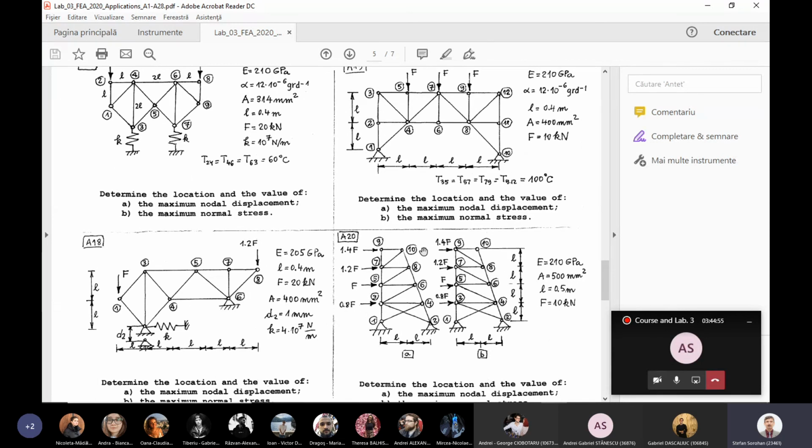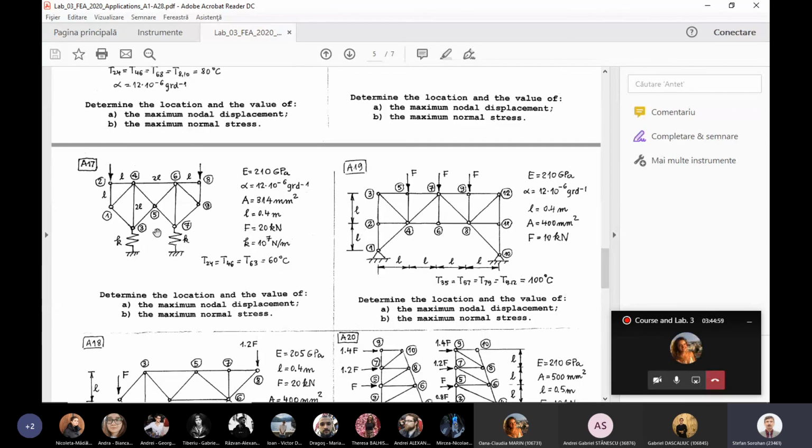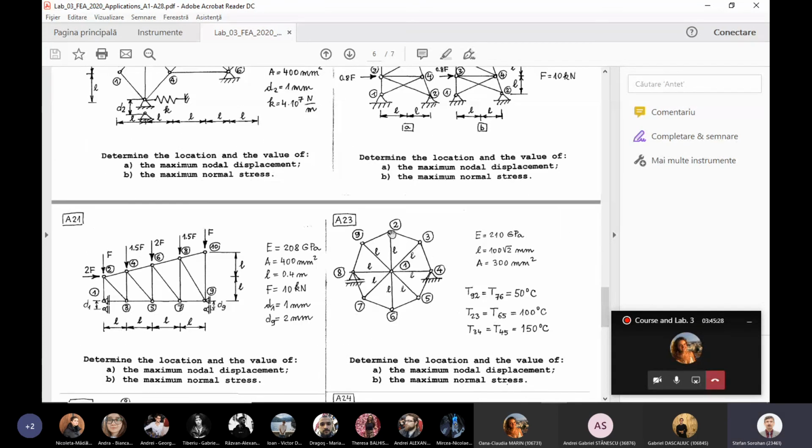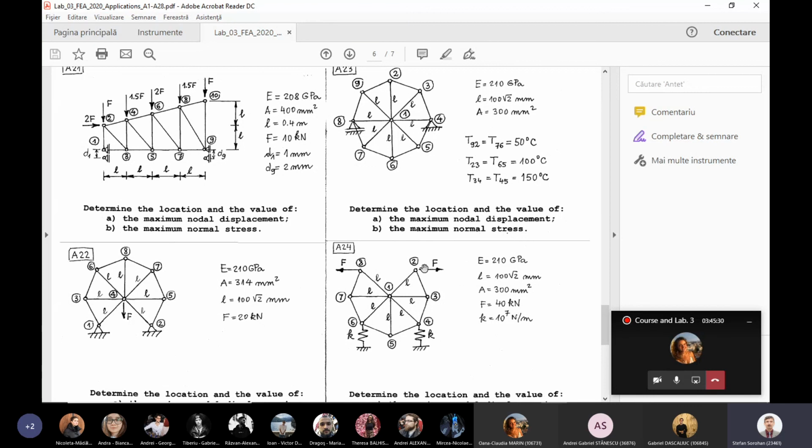It doesn't matter where. For example, let's say 0.5. It's fixed along X. And you must check after that that the reaction force here is 0. Because if you fix a point, you will have a reaction. If you fix it just to remove rigid body motion, the reaction must be 0 or very, very small. This is the idea. The remaining program will work without problem.